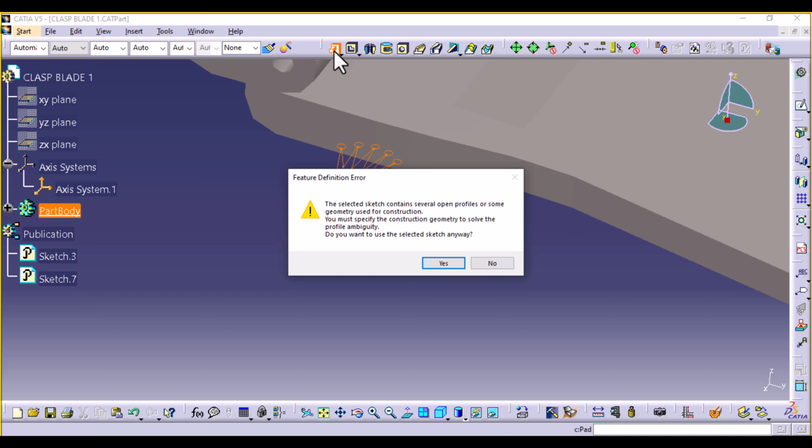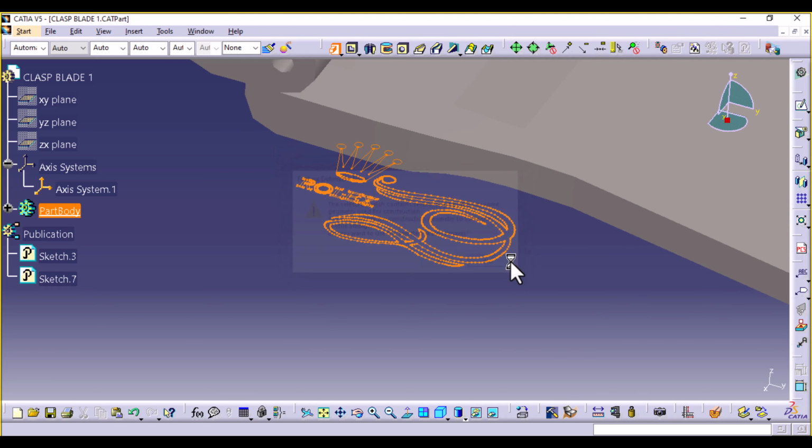And this is because when you're importing these kind of splines that were created from another workbench, I don't know if it's a bug, but even if they were closed, they kind of get some gaps in between them, and we get some non-manifold geometry. So what seems like one continuous curve is a couple of sketches which are not interconnected. They just look like they are connected, but they have some small gaps. So how do we fix that?